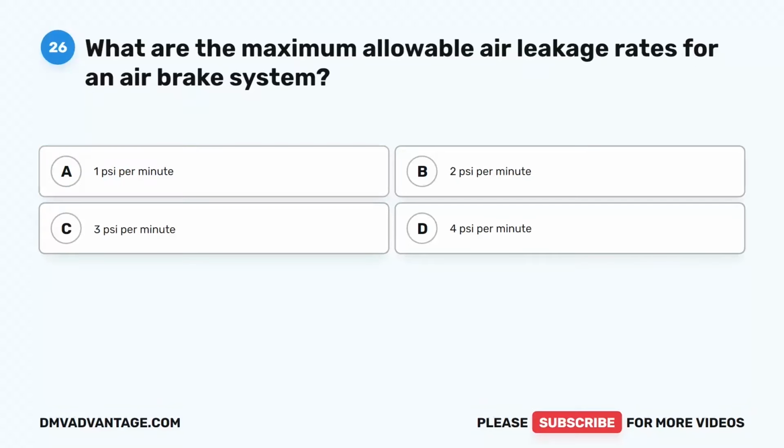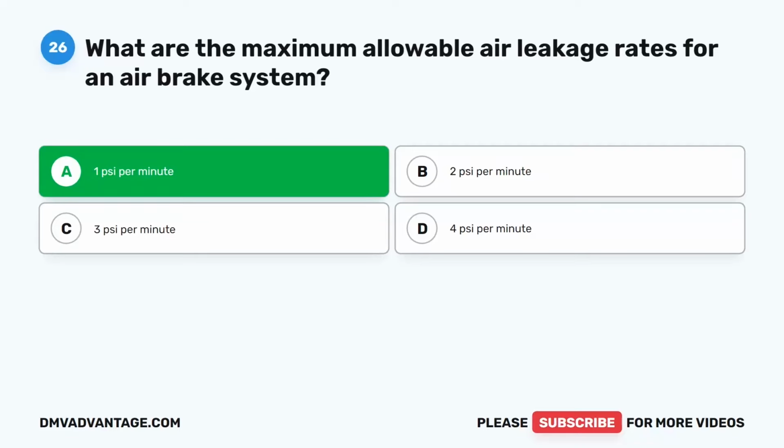Question 26. What are the maximum allowable air leakage rates for an air brake system? A, 1 psi per minute. B, 2 psi per minute. C, 3 psi per minute. D, 4 psi per minute. The correct answer is A, 1 psi per minute.